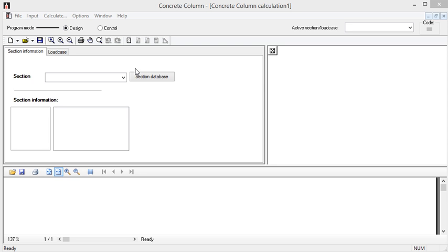In this program, the load case is superior. This means that the calculation can be performed for load cases with various inputs such as different cross-sections, buckling lengths, and materials. The data entered will therefore only apply to the active load case, which appears in the program window's upper right corner, which is important to know. Often, however, one wants the same cross-section, buckling lengths, and material properties to apply to all load cases. If so, one activates the option Linking Load Cases, as we will see later.